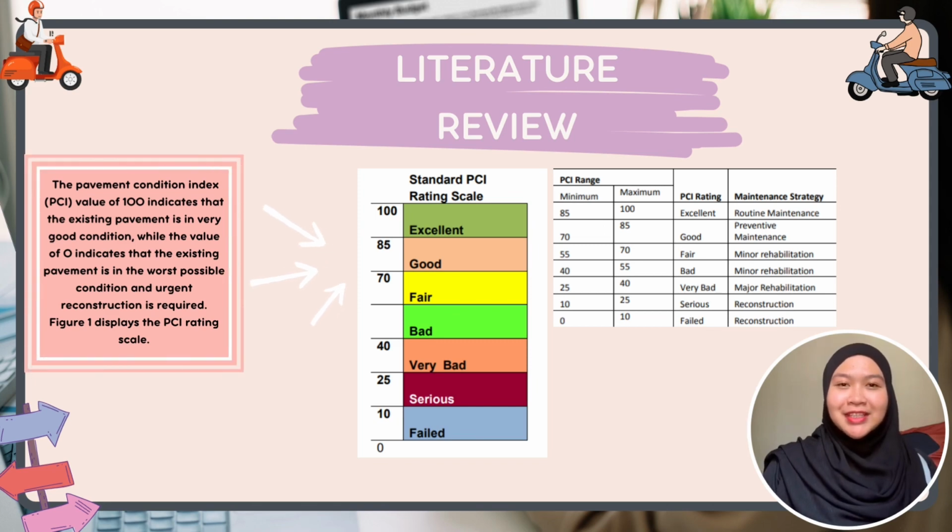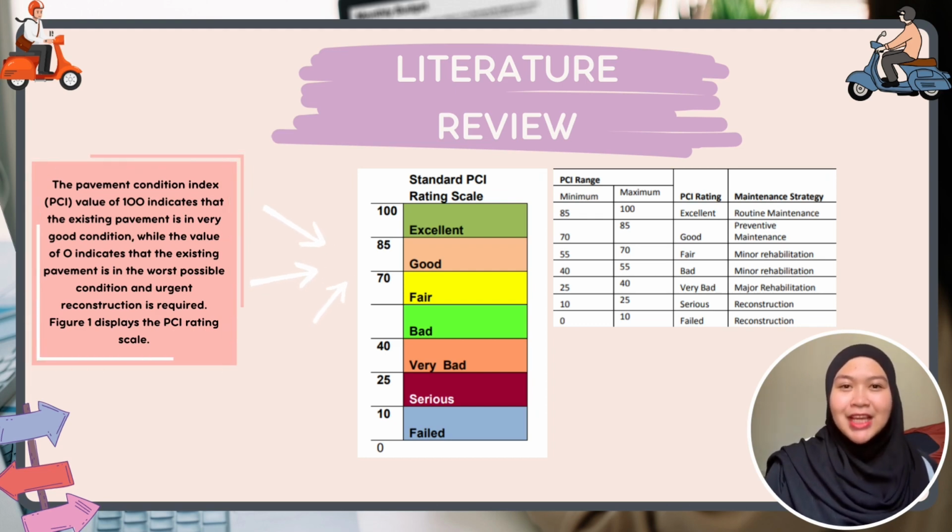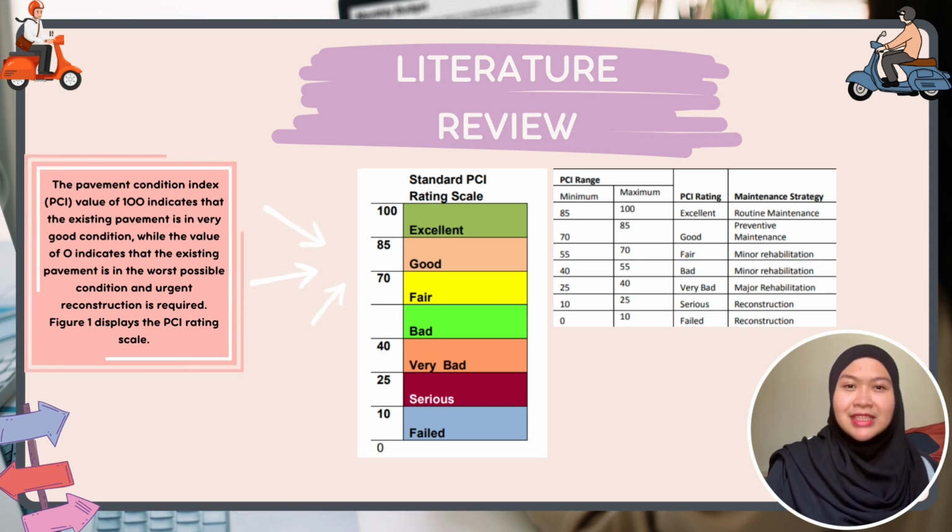According to Shahin and Walther 1990, the pavement condition index (PCI), created by the US Army Corps of Engineers, was published in 1990. The PCI test is established by visual observation of each pavement distress together with its extent and severity, and the maintenance approach can be decided. The PCI method is based on the visual examination of the pavement distress type. It provides a measure of the pavement's current condition based on the distress observed on the pavement surface, which also indicates the structural integrity and surface operational condition, roughness, and safety.